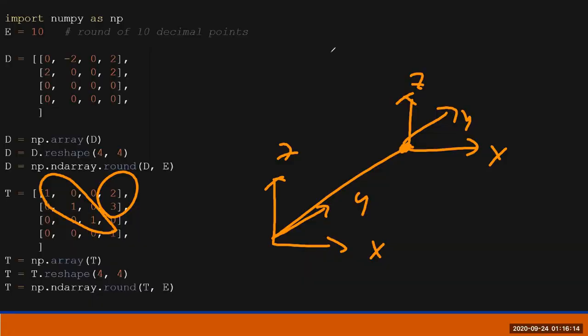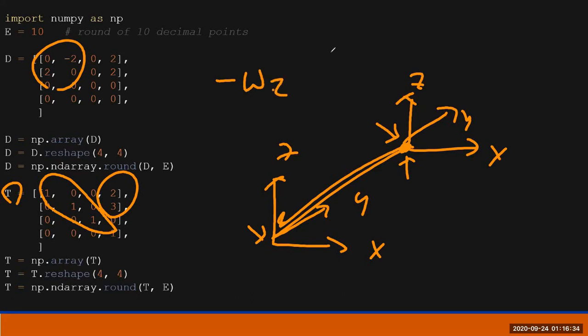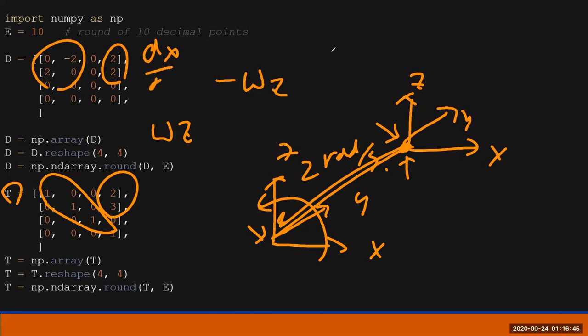And then this 2, 3 is with respect to this one. In the homogeneous transform matrix, it becomes the so-called displacement from here to here. And in the D portion, you have the radian, so you have the minus omega over here. It rotates at a speed of 2 radian per second. And here you have dy/dt, that's the away speed of the point in this frame.